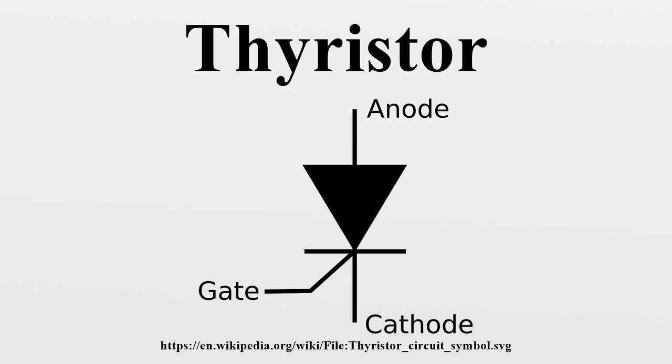The gate pulses are characterized in terms of gate trigger voltage and gate trigger current. Gate trigger current varies inversely with gate pulse width in such a way that it is evident that there is a minimum gate charge required to trigger the thyristor.